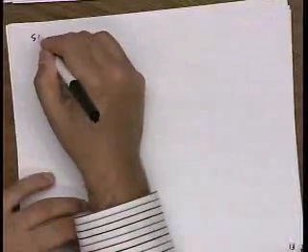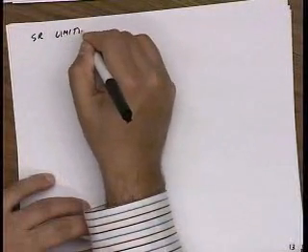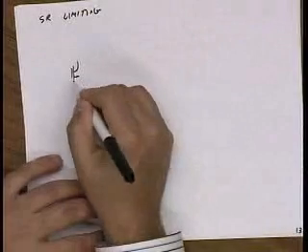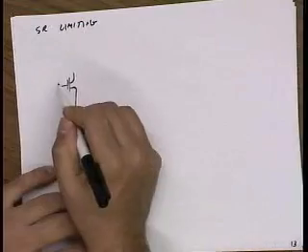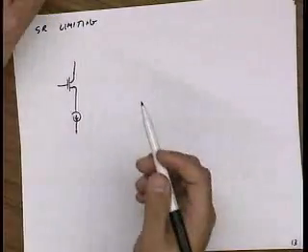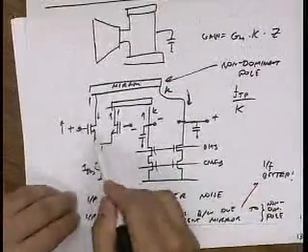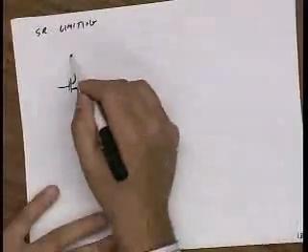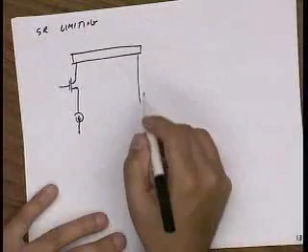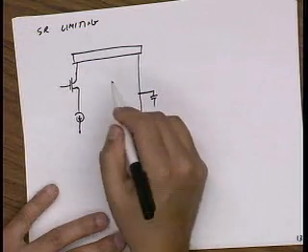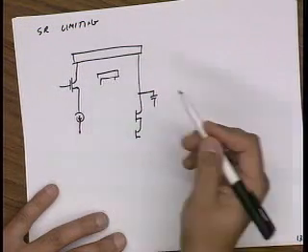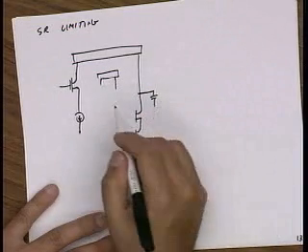Okay, one of the issues with this amplifier is its slew rate properties. So we just said the slew rate limiting is good, but I'm going to show you that it also has a problem. So let's say the input voltage is so large that only this transistor remains on. So this transistor is off. So then I have a current mirror, and this current mirror is effectively not there because it's just off.